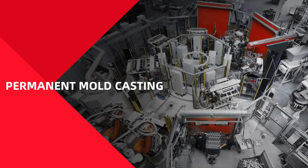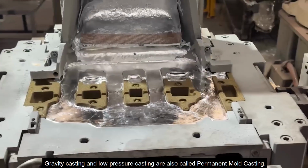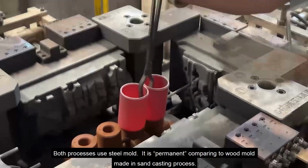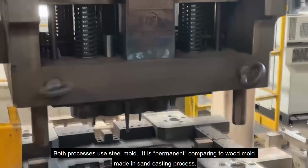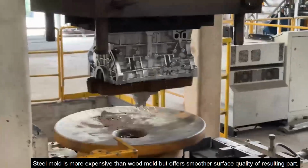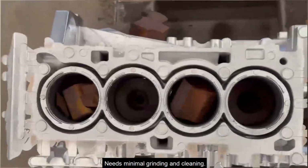Permanent mold casting. Gravity casting and low-pressure casting are also called permanent mold casting. Both processes use a steel mold. It is permanent compared to the wood mold made in the sand casting process. Steel mold is more expensive than wood mold but offers smoother surface quality of the resulting part. It needs minimal grinding and cleaning.